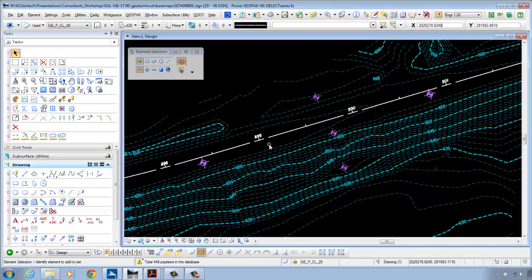On export, the gINT fence report tries to draw a best fit straight line between the centers of all the borings, and it can't do that, so it blows up and doesn't export the graphics for that last boring. I have that bug reported to Bentley. I don't know when or if they're ever going to fix it.